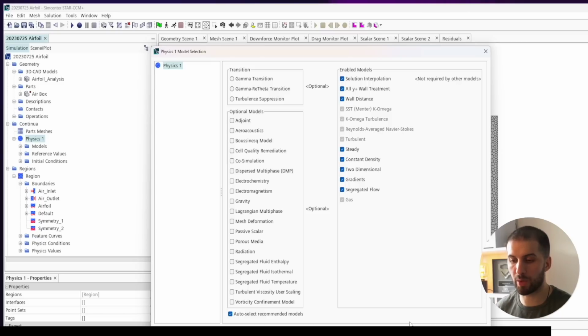So really think about, especially when setting up the physics and boundary conditions, that the choice of turbulence models is really crucial, and it goes hand in hand with the meshing. If you screw up the mesh or the turbulence model, you can start from scratch. So always think about how you want to approach a simulation: start easy, and then increase the complexity.